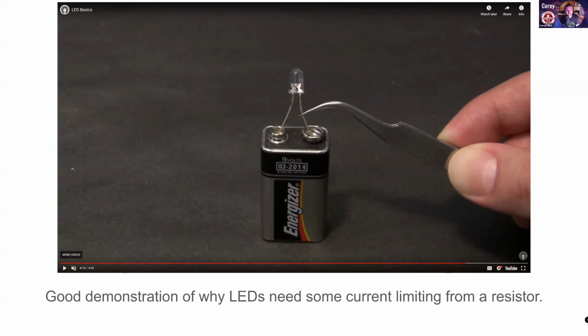That's probably the case. LEDs are also luckily very cheap. So it's good to do this once or twice just to see what it looks like in the safer failure mode rather than the glorious explosion mode. But it's good to see. Yeah, these are definitely fun to make happen. They're cool to do, but I would say that that's going to be your most likely failure mode if you just can't figure out why the LED isn't working. It's either that you've got a 10K resistor in with it, or maybe you killed it and you can't tell. And if you look really closely, you can sometimes see the charring inside. So it's worth giving a close look at them.